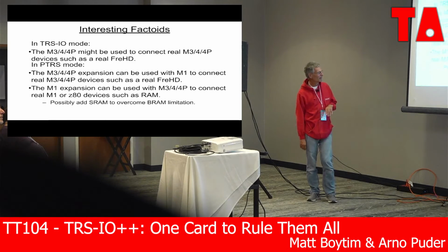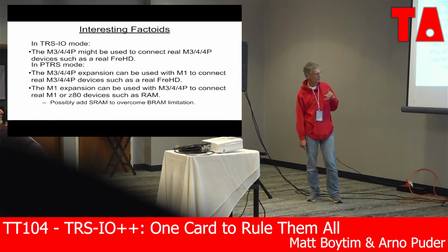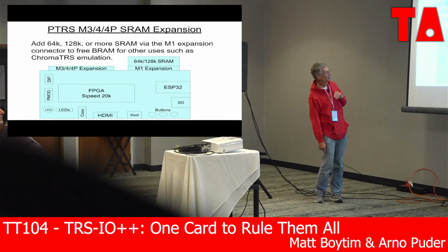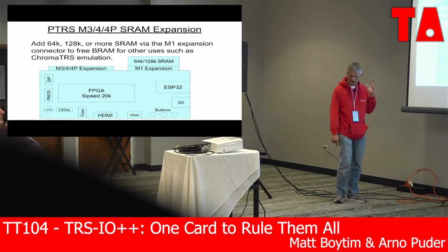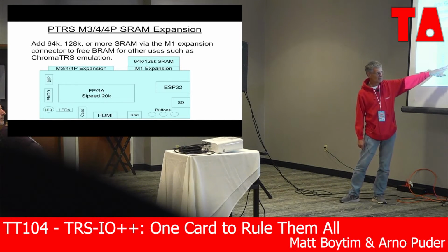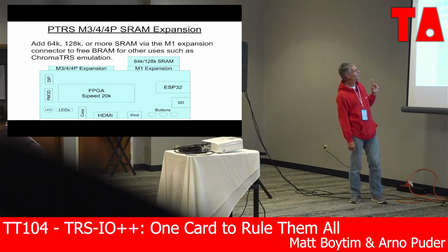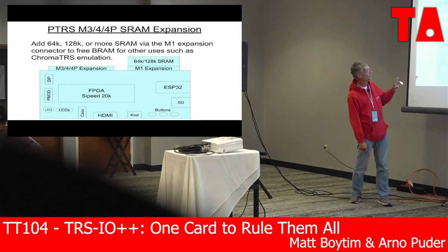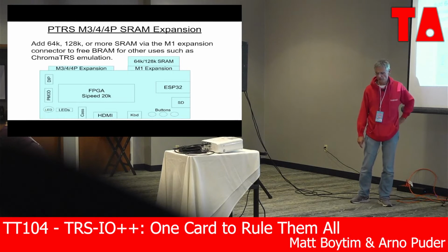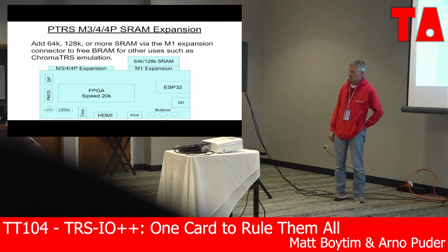So go to the next slide. One of the possibilities, I mentioned how we're limited by the amount of memory. Even though we've got this large SDRAM here, I'm not sure we can make use of it. But one possible solution is that we could connect a 64K or 128K RAM to the Model 1 expansion connector, because it's essentially the Z80 pinout.